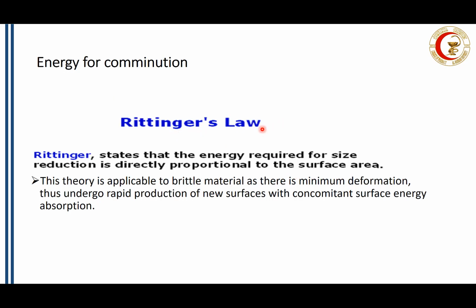Now, Rittinger's law states that the energy required for size reduction is proportional to the surface area. What we mean by this is that the energy required for size reduction is directly proportional to the increase in the surface area of the final product. Rittinger's law is applicable to brittle material, as there is minimal deformation, thus undergoing rapid production of new surfaces with concomitant surface energy absorption.